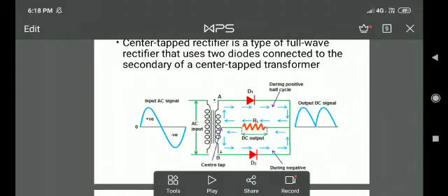So what we see, the anode of diode D1 is connected to the positive terminal, whereas the anode of diode D2 is connected to the negative terminal, to the point B. So diode D1 is forward biased and diode D2 is reverse biased. So the output passing through the load resistor is from point A, D1 and then RL to point C. In the lower half of the circuit, as diode D2 is reverse biased during the positive half cycle, no output is produced in RL through diode D2.